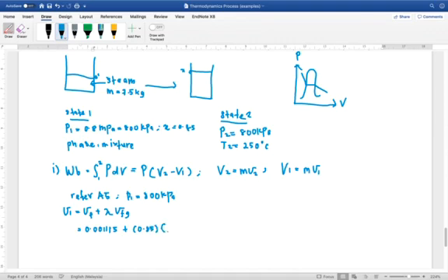So you have to take vg minus vf: 0.24035 minus 0.001115, and you will get the answer for specific volume at state 1, 0.20445 meter cube per kilogram.